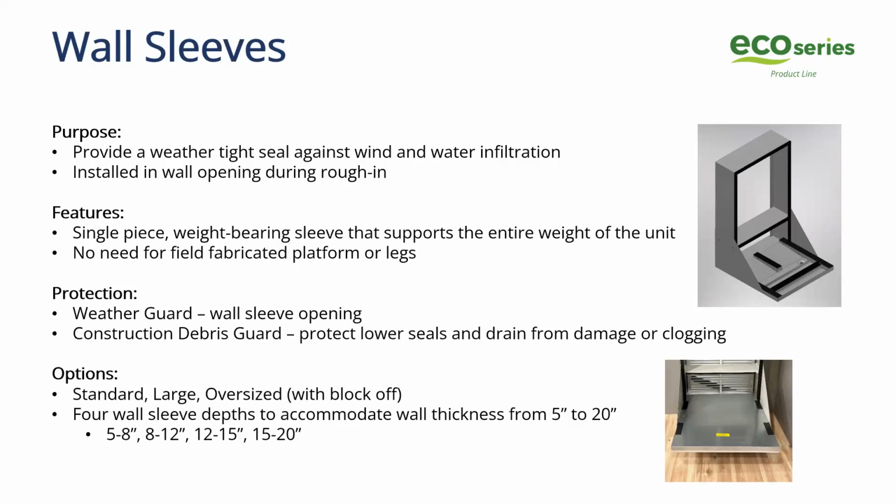Now, obviously the walls around the wall sleeve would need to be properly insulated. And then the walls around the closet, we typically look to make sure that they're drywalled on the interior of the closet, more for sound attenuation purposes than keeping it warm or not. But we definitely want to make sure that closet is kept at a reasonably warm temperature, just so you don't have any issues with anything.